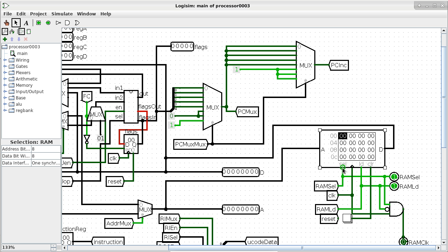LD over here is the abbreviation of load. It controls whether we want to write to the RAM component or read from the RAM component. When LD is a 1, we are reading. When LD is a 0, we are writing. And then the last one is clear, which is analogous to reset of our D flip-flop discussion from Tuesday. In other words, you can look at this as a gigantic array of registers where the A port specifies which register you want me to access this time.